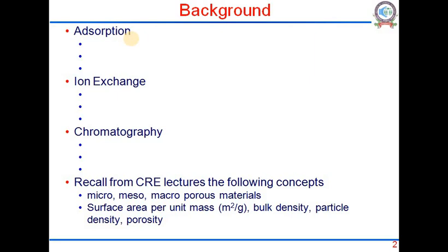Very commonly they are used to remove coloring impurities from solutions before you crystallize them in pharma products, or, for example, when you want to do effluent treatment, some coloring matter remains after the aerobic treatment, and you would want to do adsorption to remove the coloring matter.